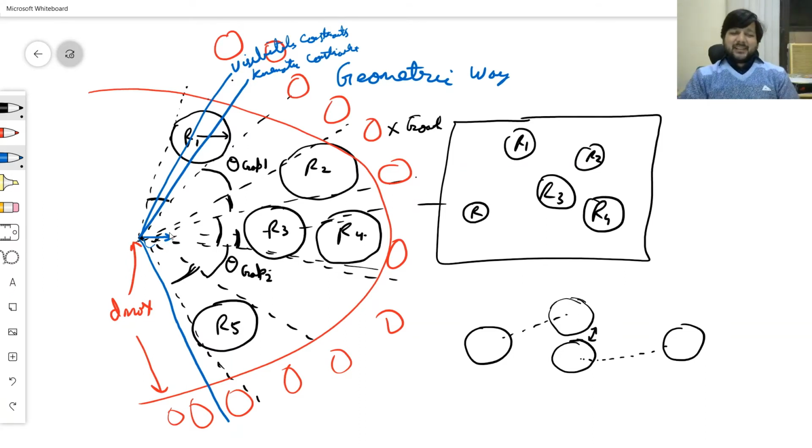I'm traveling at a certain velocity v. Depending upon the velocity, there's only a specific curve that I can take. I cannot turn more than that radius. That means my immediate velocity has to be between some kinematic constraints to some other kinematic constraints. So that's the visibility constraints and that's the kinematic constraint. So this is the effective range from which I can choose the angle, which will be feasible, which will be realizable.